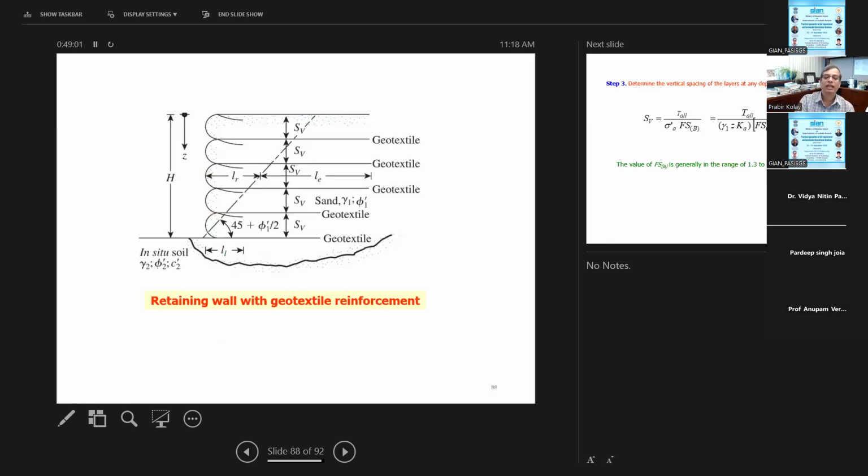And then obviously when you use the geotextile, there should be some lap length over here. So basically you see over here LL. When you put a geosynthetic material, put granular soil, and then put a little bit of lap, overlap the cover. There is no skin over here. And then you put a layer of sand again, and then put a geotextile, and then put the lap length over here. So basically what you need to do is find out LE and LR, same as before, the Rankine failure lines, and the 45 plus phi by 2 angle. So this is for geotextiles.